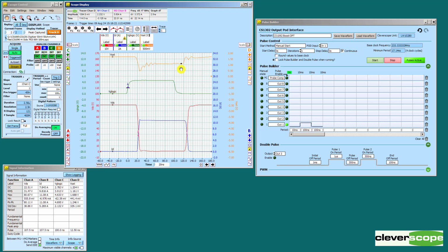So from here on, Vsat is accurate. We can see the change in voltage, and it's about 7 millivolts. I'm guessing that corresponds to the 100 milliamp change we saw. We could work it out based on the RdsOn of the FET.